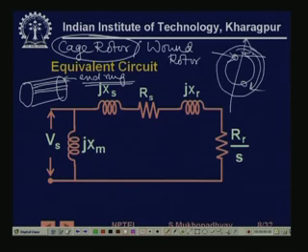In the direction that the stator MMF is rotating, because by Lenz's law, if the rotor exactly aligns and moves in synchronism with the flux rotating at synchronous speed, then there is no net rate of change of flux around the rotor coils and therefore no EMF. So, by Lenz's law, the rotor will try to eliminate the cause that is causing the current to flow.